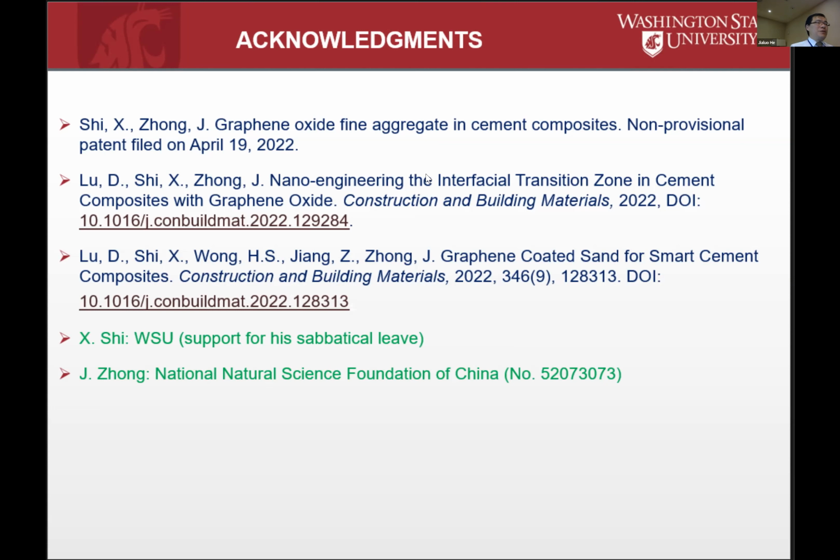We actually published another paper a few years ago in Cement and Concrete Composites where we nano-engineered the ITZ, the interfacial transition zone of coarse aggregate. But in that case, we had to use a nano-engineered mortar because the initial experiment by my student didn't quite work with this simple approach. The beauty of this one is really simple, right? You don't use a mortar, you just soak it and then you put it back in and you're seeing this roughly 40% improvement. Sorry, what's the other question? Right, yeah. Coarse aggregate is a little more challenging, but we hope to get there.